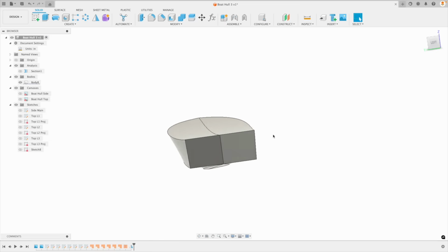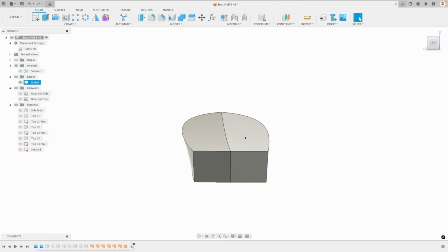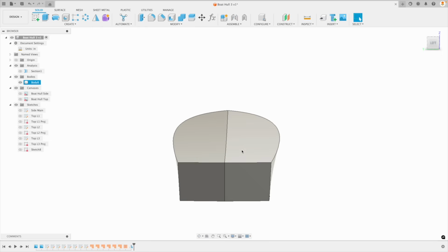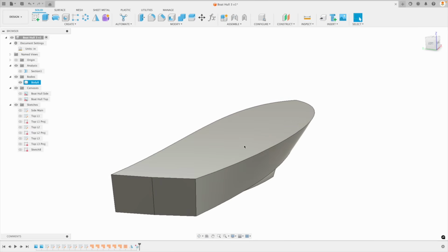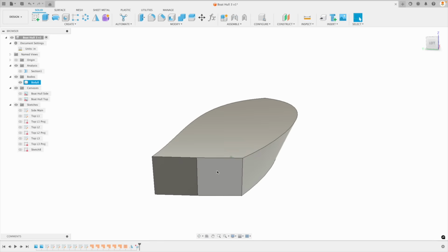Now, this right here, let's take a look. I believe that we can grab one of these faces because we could actually connect them together to be one face. Let's just see. I'm going to select one and press delete and see what happens. There we go. So sometimes when the faces match up perfectly, like in our case they did, we can select one of them, what you just saw, and it will delete it and create this perfect single surface connecting everything together.